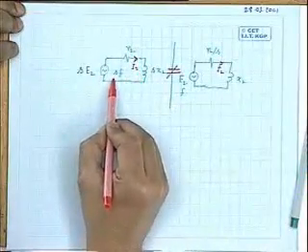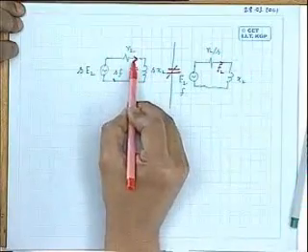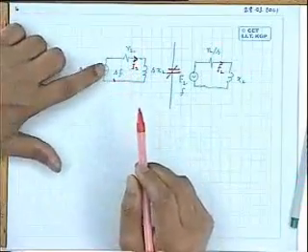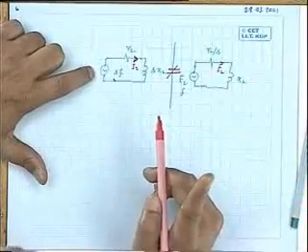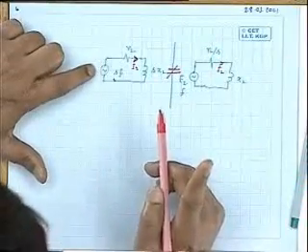See, in the first case, it is not very difficult. In the first case, you are sitting on the rotor, and I2 is the current. What is the power loss in the rotor resistance? Rotor resistance power loss is I2 square R2, the actual rotor resistance power loss.